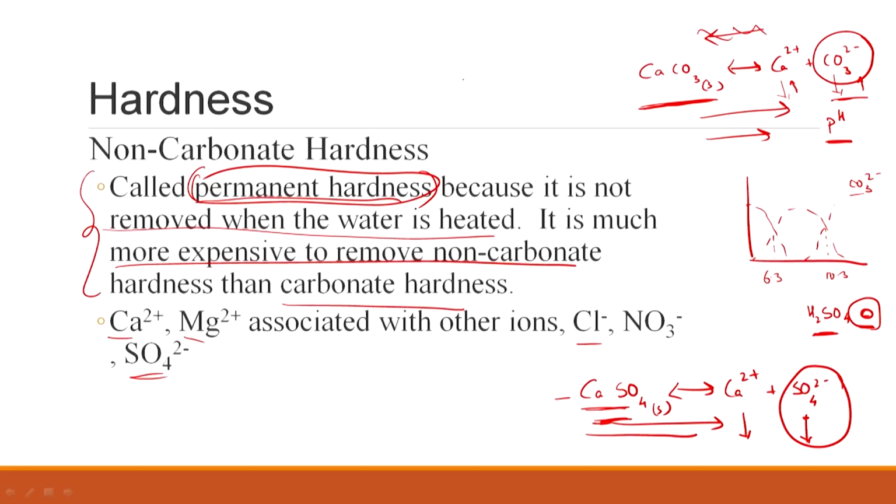And this is an issue even in your water treatment plants. Let us say this is your membrane and you have these deposits on the reverse osmosis membrane. Over time, your membrane is going to get choked, and the mass flux is going to decrease. So, you have to increase the pressure a lot, which is costly. That is the reason I typically do not like RO, because you do not need that level of treated water for most of the kinds of water that we come across, but again that is an exam question. We will discuss that later.